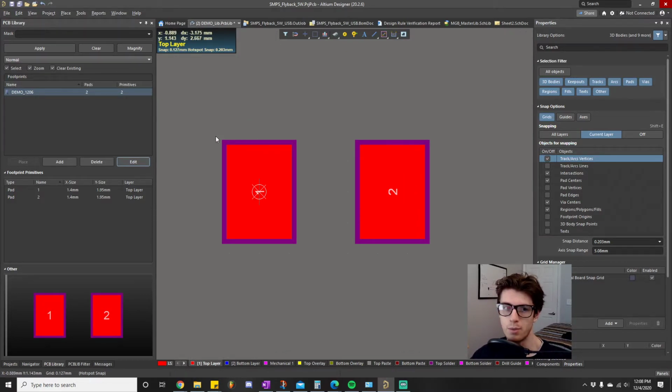So we're essentially done. This is the bare minimum that you need for actually creating a board that will work. However, we want to go a little bit above and beyond, and we want to make what I would say an aesthetically pleasing, professional looking footprint. There are two major things that I want to add to this footprint to make it look that way. One thing is I want to put a little bit of ink on the top overlay. You can call it some guidelines.